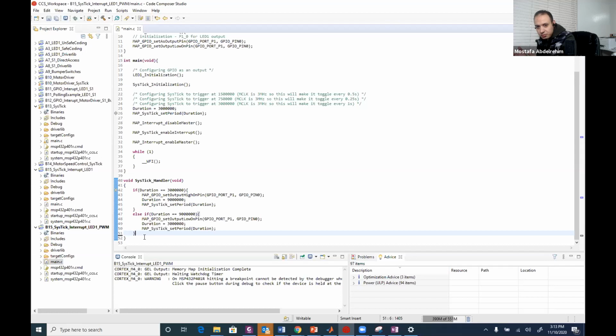No, I'm just asking, what's the benefit of using an interrupt handler specifically instead of a timer or just a case statement, like a switch or if? Using interrupts all the time enables you to do something else. So here in the while loop, you might do any other things.